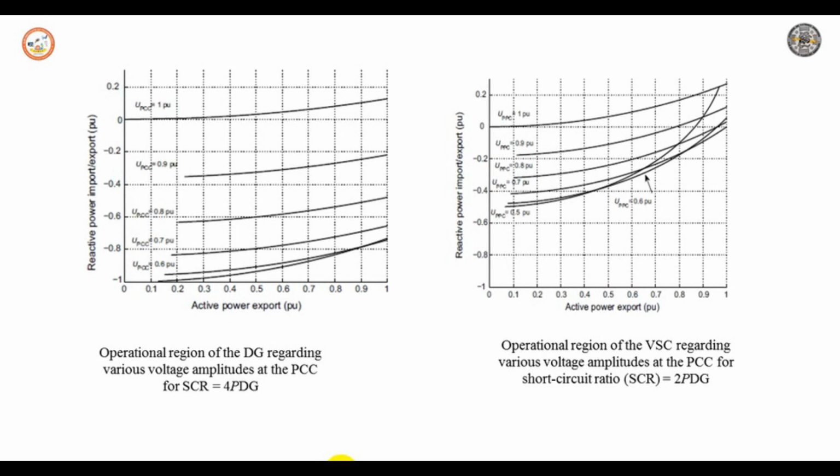The operation limitations mentioned above are due to the network parameters, and they give theoretical boundaries for local voltage regulation at the PCC. For an ideal generation plant, there are also operational limitations due to the physical configuration of the DG itself and its control algorithm. Regarding the VSC interface, there are basically two limitations that affect the transfer of reactive power through the feeder.